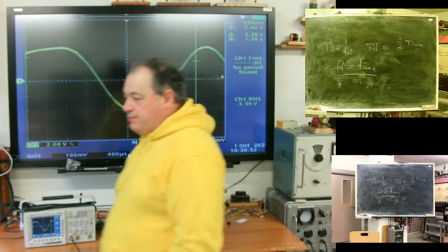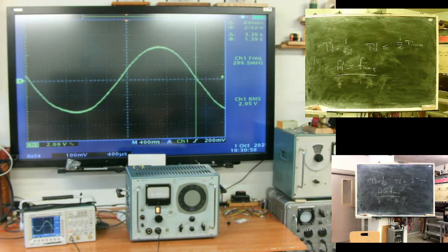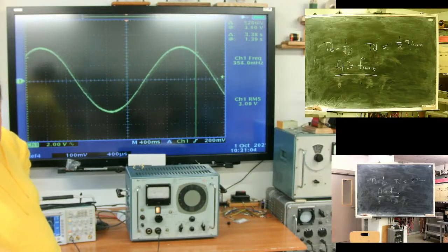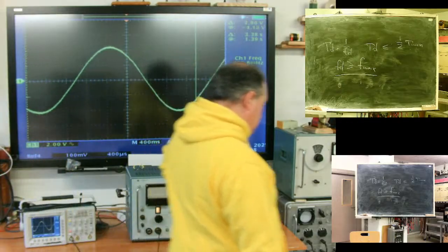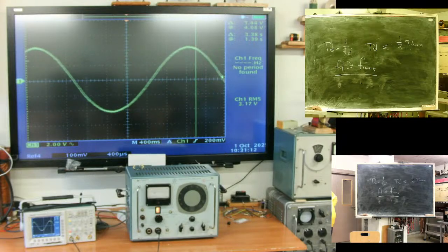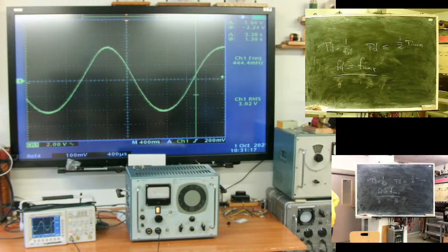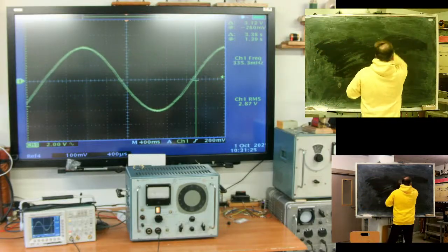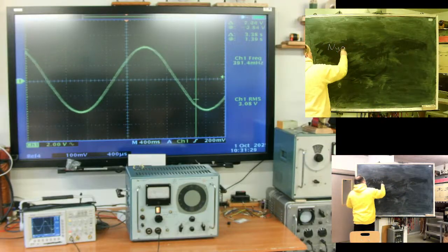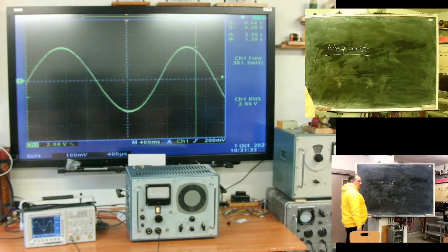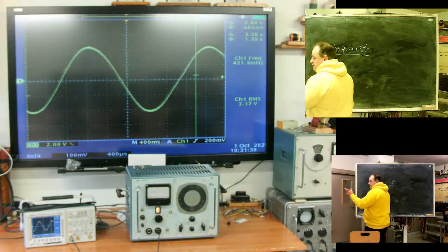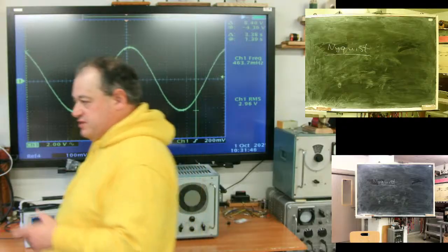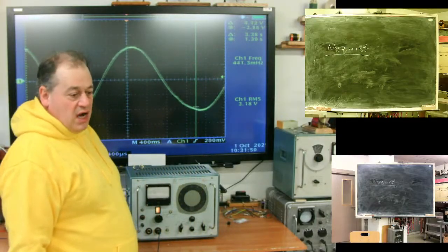The sampling frequency to represent our original process signal correctly should be at least twice the maximum frequency component of our signal. The name for this is the Nyquist frequency. The idea of the Nyquist frequency, again: the sampling frequency of our digital system should be at least twice the maximum frequency in the observed signal. Or you get rubbish instead of results.